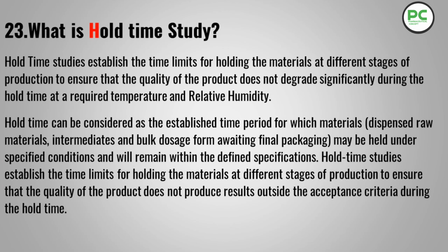What is hold time study? Hold time study establishes the time limits for holding the material at different stages of production to ensure the quality of the product does not degrade significantly during the hold time at the required temperature and humidity. Hold time can be considered as the established time period for which the material, dispensed raw material, intermediates and bulk, awaiting final packing may be held under the specified conditions and will remain within the defined specification. Hold time studies establish the time limit for holding the material at different stages of production to ensure that the quality of the product does not produce results outside the acceptance criteria during the hold time.